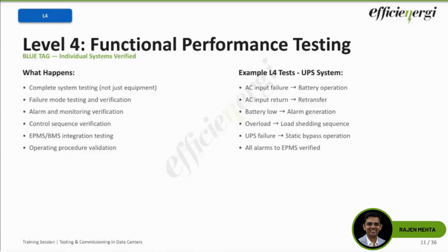So here any deviation must be documented and resolved. Now some common L4 issues which I mentioned: alarms not appearing in the EPMS, wrong severity, control sequence not matching the sequence of operation, communication timeouts happening. All of these can be common issues that you can expect during the L4.